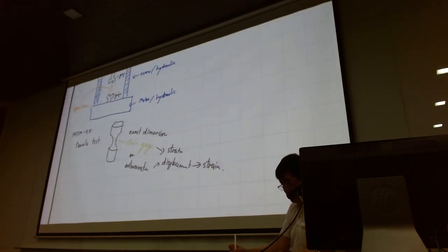And then of course you will be using caliper. Caliper would be the device like this to measure the diameter of this. Caliper would measure the diameter of the specimens so that you can get the area.